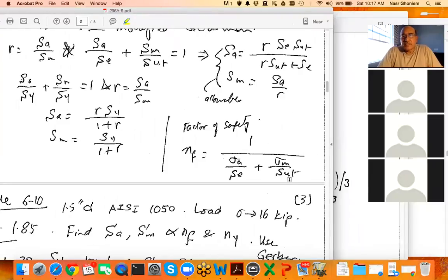So these are the two key ideas. One idea is how to construct the S-N diagram. I have to figure out whether I have low cycle fatigue or high cycle fatigue. The second idea is how to protect against failure on the first cycle, and how to determine the safety factor considering the intersections between the load line and the criteria lines that we talked about, and also with the Langer line.